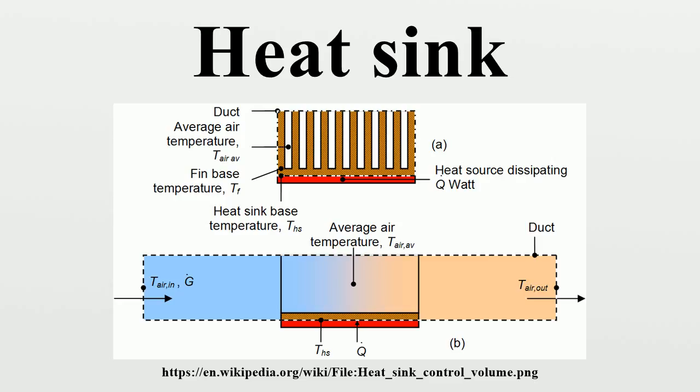It only models a system in thermal equilibrium, and does not take into account the change in temperatures with time, nor does it reflect the non-linearity of radiation and convection with respect to temperature rise. However, manufacturers tabulate typical values of thermal resistance for heatsinks and semiconductor devices, which allows selection of commercially manufactured heatsinks to be simplified.